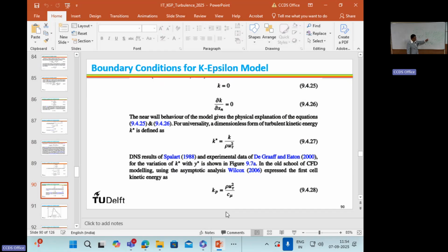This updated velocity influences the subsequent cell velocity in the next iteration. When solving the next time step or iteration, this velocity influences this velocity, so from this value this gets updated, and iteratively this process continues.